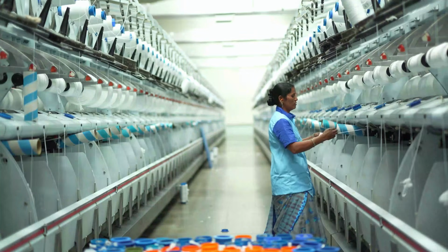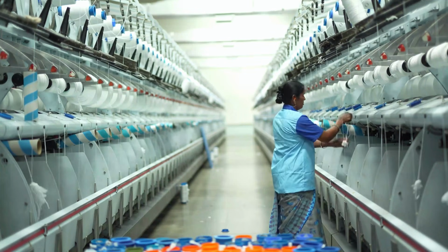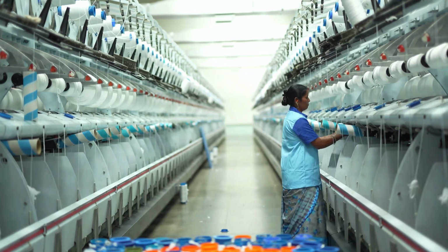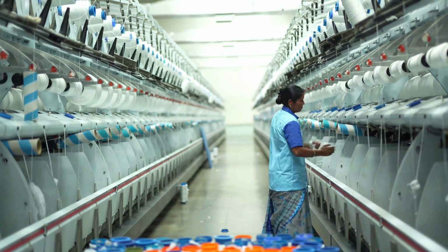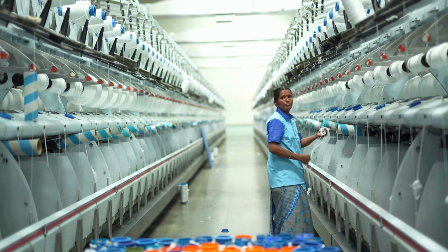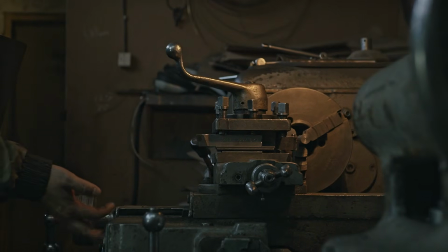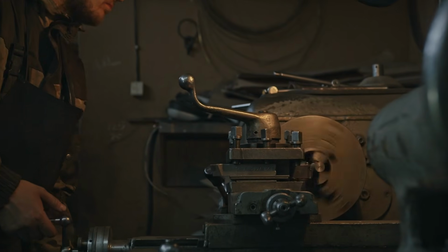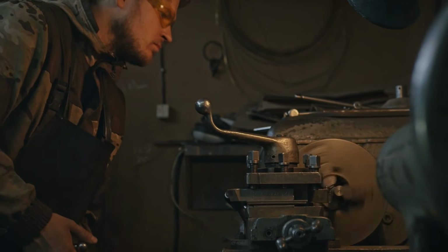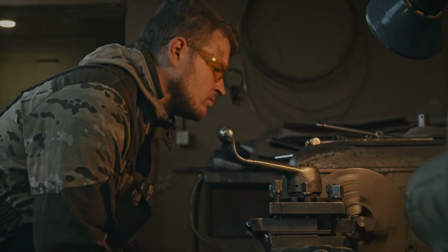That's the trap. Surface speed stays flat. RPM does not. As diameter shrinks, RPM climbs, and there's no upper limit hiding in G96 itself. Near centerline, the math goes to infinity. The motor doesn't care. The chuck does. Every chuck has a max safe RPM. Past it, centrifugal force overcomes the jaw grip and the part walks.